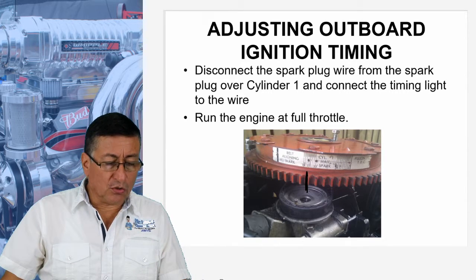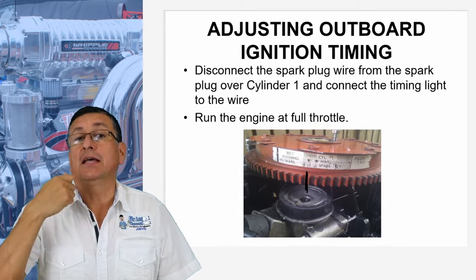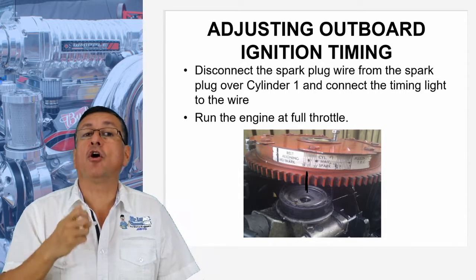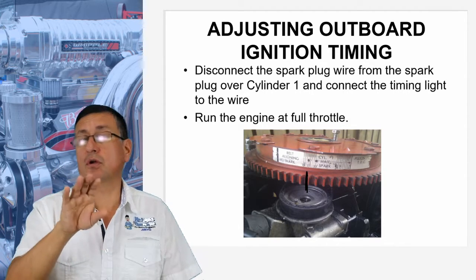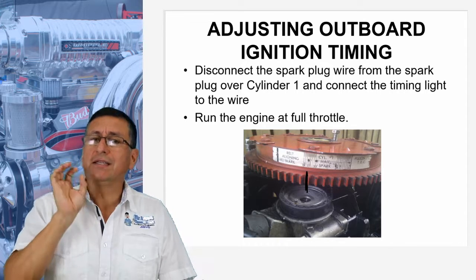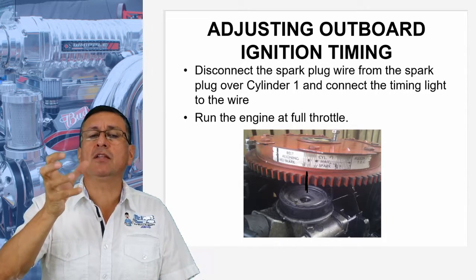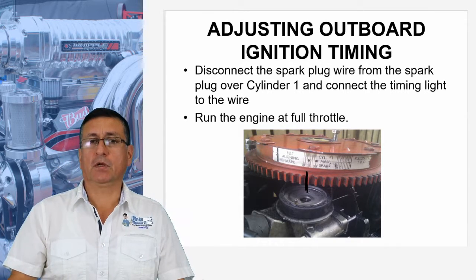In wide open throttle, the engine calibrates the timing, advance or retard, automatically if the engine is fully electronic with direct or indirect fuel injection. If the system is electronic with computer, the computer calibrates the timing automatically. Alright?